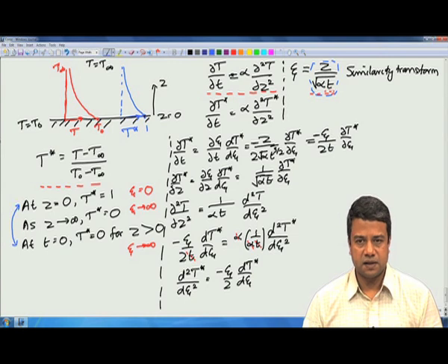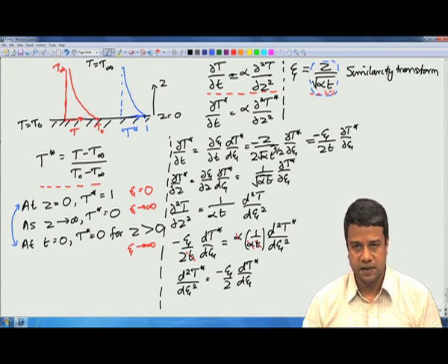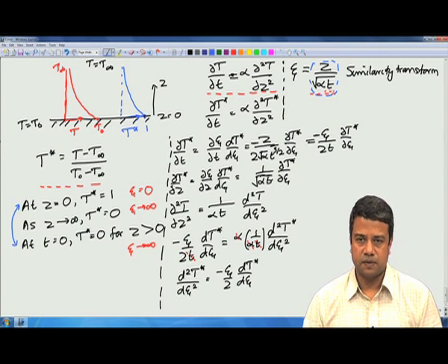Similarly, the heating starts at t equal to 0 and continues for all time, t going to infinity, so we were not able to find scaling for the time either. There was a deficit of dimensional quantities with which we could scale the spatial dimension and time, and the only parameter in the problem is this thermal diffusion coefficient alpha.